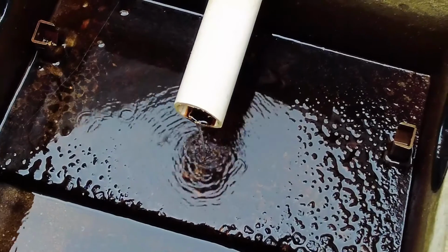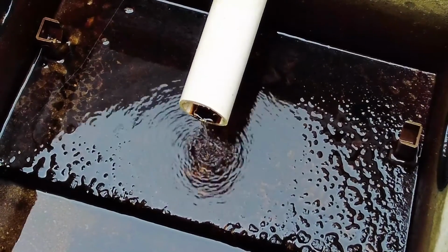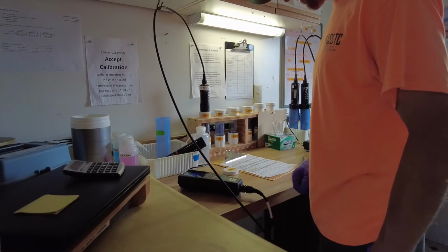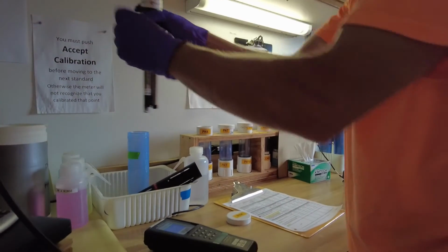So for laboratory samples, you need to pay attention to the bottle type, the preservative, and ice, whereas in the field, you're taking them right there, so just make sure you're in the proper location and free-flowing. Yeah, free-flowing, and also it's the calibration of your instruments, which is big. It's very essential, particularly pH. For instance, here at the test center, we calibrate our pH meter daily with 3 standards.